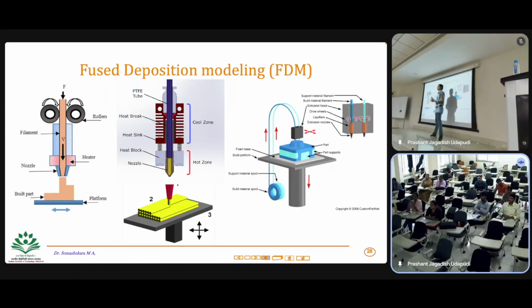But sometimes, for example, you want to print more material and increase the printing speed, so there you need to go for a bigger nozzle. Sometimes you may be mixing some powders, so there you may have to go for a slightly bigger nozzle, and make sure the material does not settle at the nozzle, otherwise it will clog.